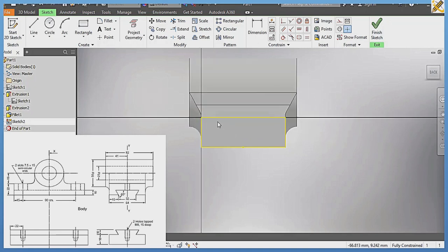So it makes this particular area to be what? To be airtight. You understand? You know, in Inventor, if you draw lines, or if you are drawing a plane figure and the figure is not closed, you know it will be impossible for you to extrude such figure. So in order to avoid that, that is why I created that project geometry here, so as to tighten all the edges. That is the reason why I do that right there.